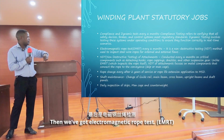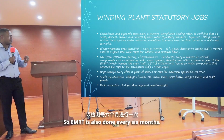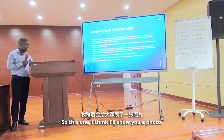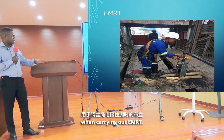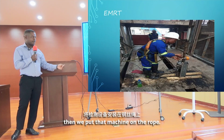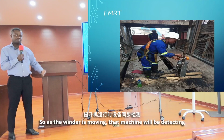Then we've got the electromagnetic rope test. EMRT is also done every 6 months. For this one, I think I'll show you a photo. In this picture, it's showing how the machine is set up when carrying out EMRT. The shaft is closed. We put a working platform, then we put that machine on the rope. As the winder is moving,